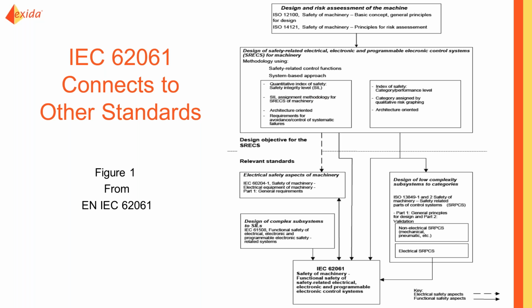they give general guidance. The machinery safety standards are focused more on when you get to the SIL determination and then how do you design a system, and they have very little description of operation and maintenance phases. But this shows where you can find these ISO standards for risk assessment. Use 62061 in here for the design of a safety-related electronic control system. And at some point, you might even go to 13849 for simple systems.